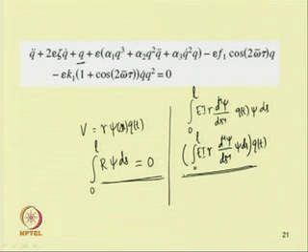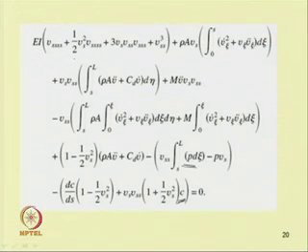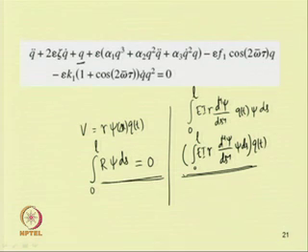So, in this way, by taking the terms term by term, one can convert this spatio-temporal equation to a temporal equation. And one can note that in this temporal equation, this time varying term is a coefficient of q. So, this is a parametrically excited system.